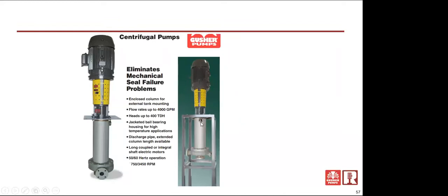and then we would take a pipe or a hose from this port right here, either back to the suction side, so it could be brought back into the suction, or from this port, it would be pumped back over the tank so it can drain back to the tank. But this becomes a sealless pump mounted outside of a tank.